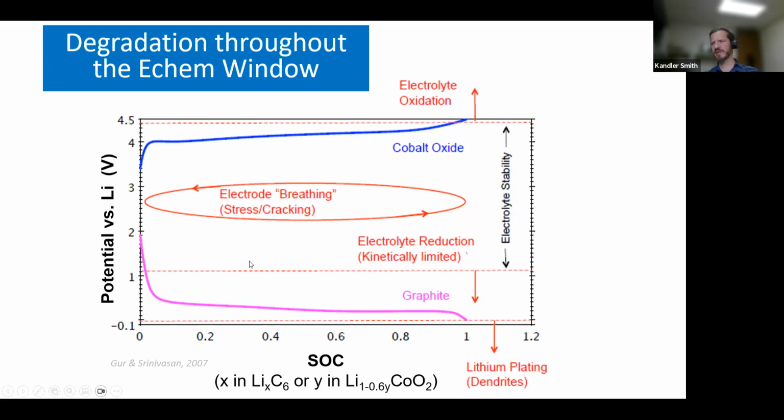And then for calendar aging versus cycle aging, in typical light duty automotive, I see that perhaps calendar life is about 1/3 of the degradation and cycle aging is about 2/3 of the degradation. They're generally additive. For a commercial implementation of energy storage, you're cycling every day over a wide range, so in that case cycle degradation is probably going to be very dominant. But I'd say calendar degradation is still something you need to pay attention to.